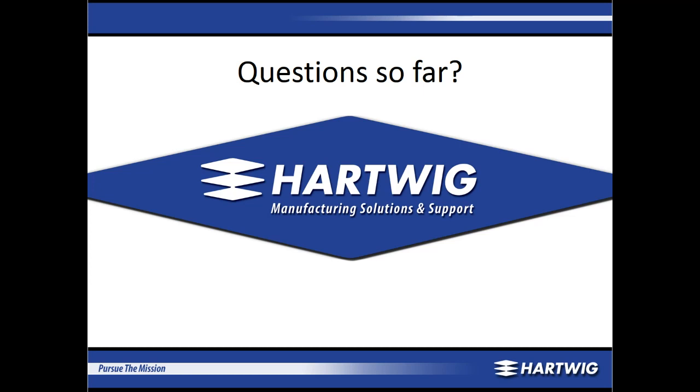Any questions so far? Is there a G code that will force rigid tapping and it not be dependent on the parameter setting? Yes, I forget the G value off the top of my head, but there is a G code for rigid tapping that's separate from float tapping if you have both and you wish to use one or the other.